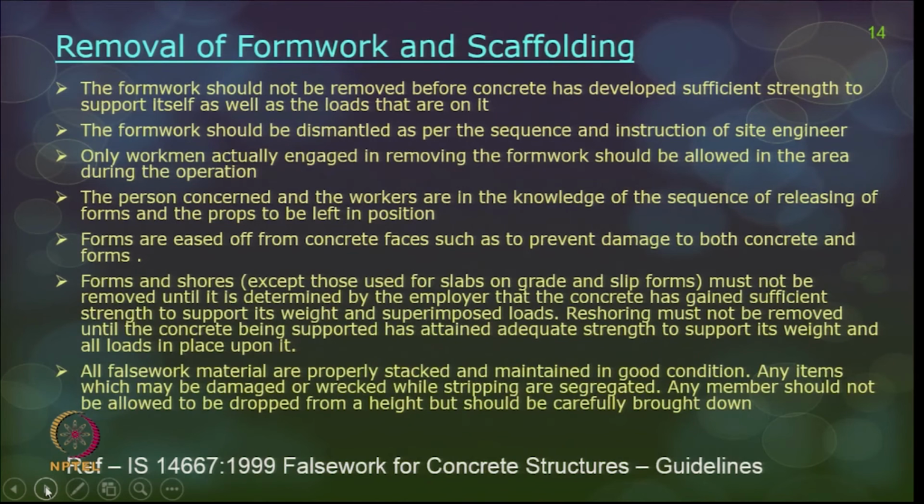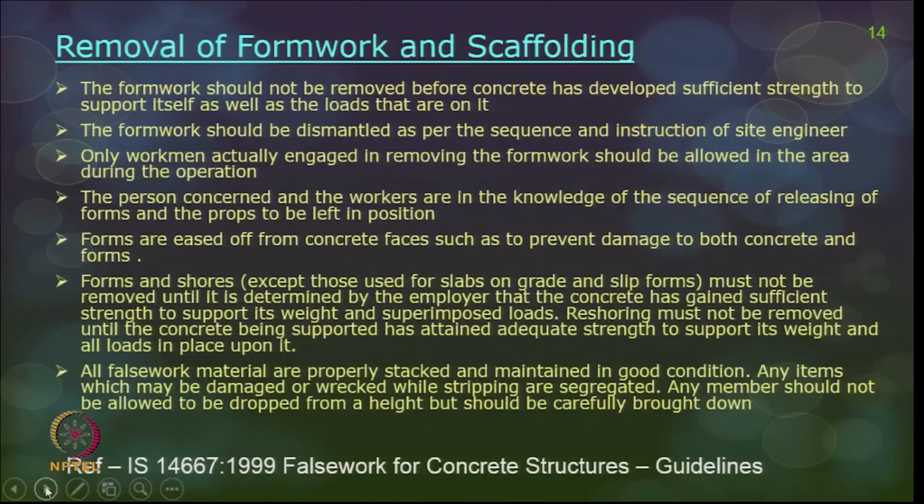The formwork should be dismantled as per the sequence and instructions of the engineer or as given in the formwork drawing. The sequence of removal of formwork should be maintained at any point of time, and only workmen who actually know the procedure of removing the formwork should be allowed in the area, and they should only be removing it as per the sequence. The person concerned and the workers who are actually stripping off the formwork should know the sequence of releasing the formworks, and accordingly should know the location of props left in position.